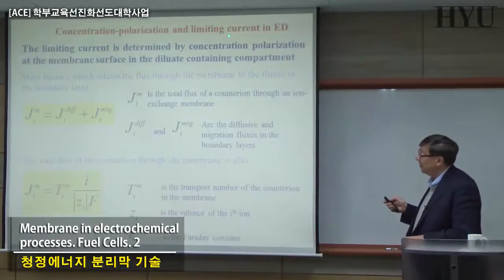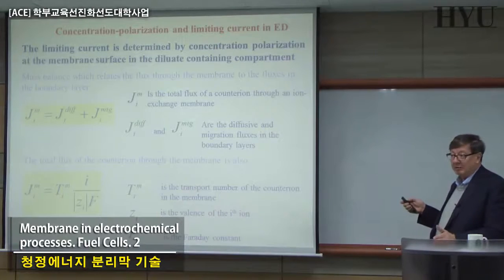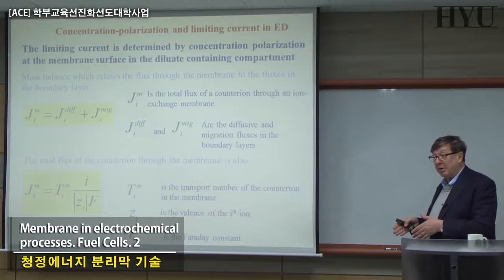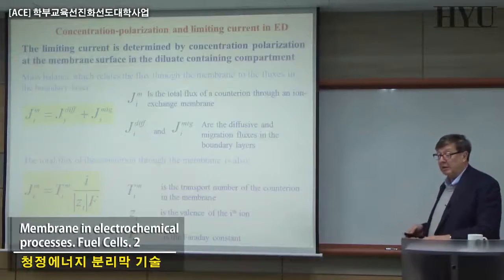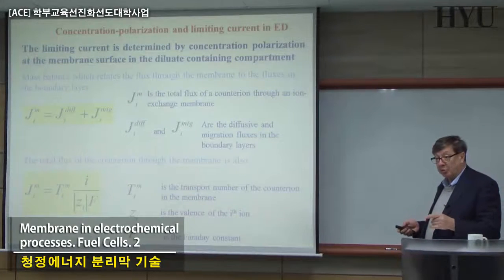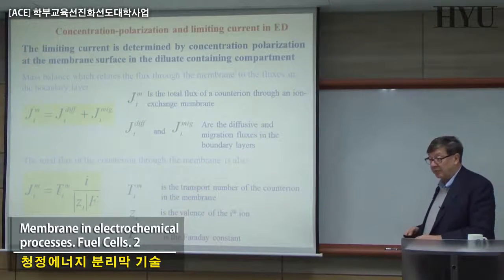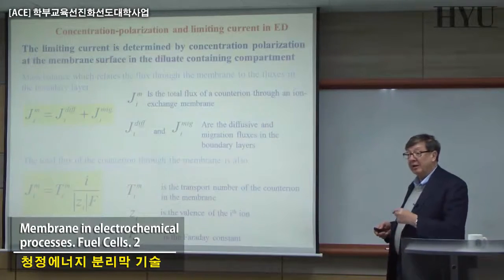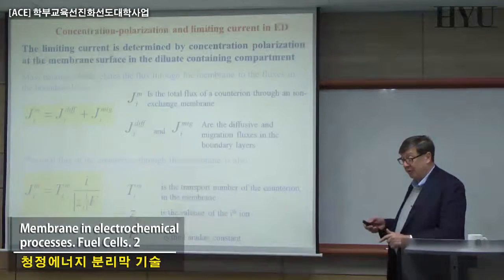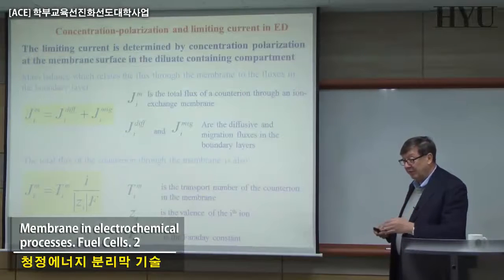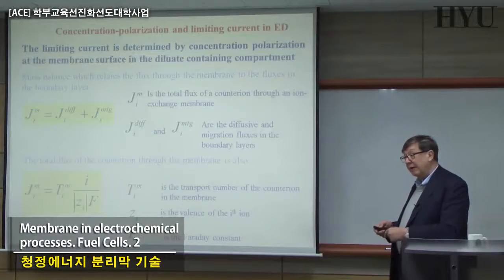That is the same kind of limiting current that we have in the electrodialysis process, just the same story, and the origin is related to the property of the membranes, as in traditional membrane operations, because some of the ions, and particularly in fuel cells the protons, which transfer the current from one side of your membranes to the other, can have a much different velocity moving in the compartment, in the solution, and in the membranes.